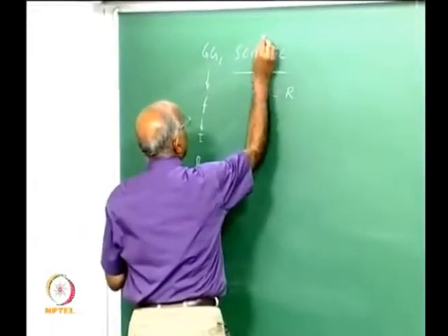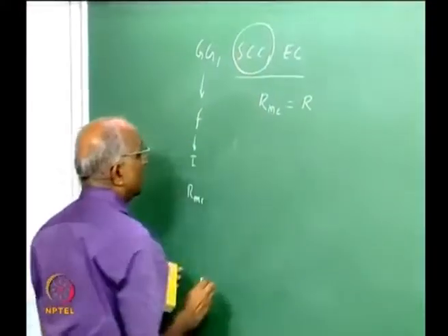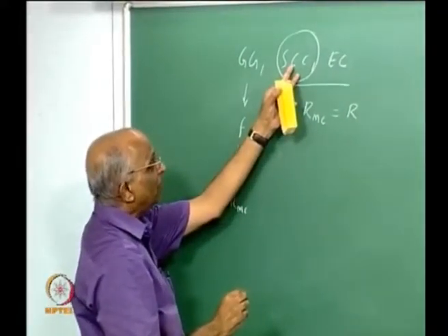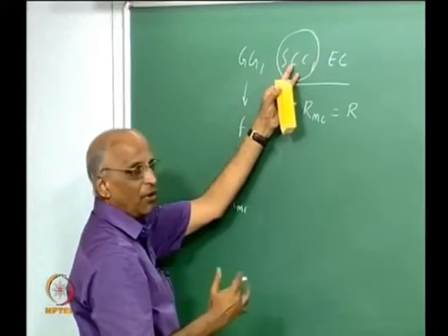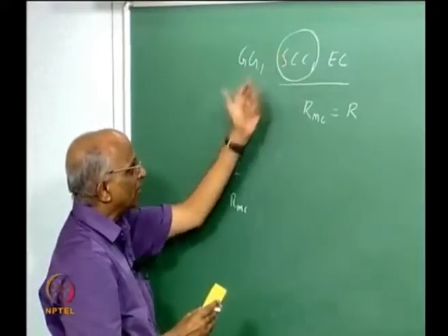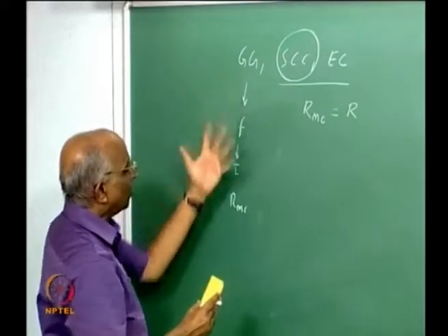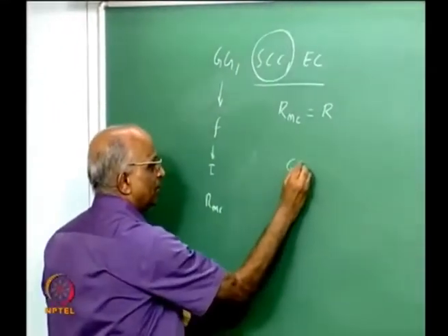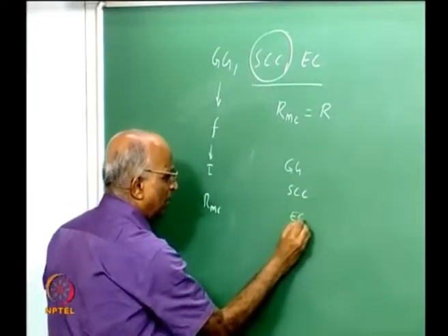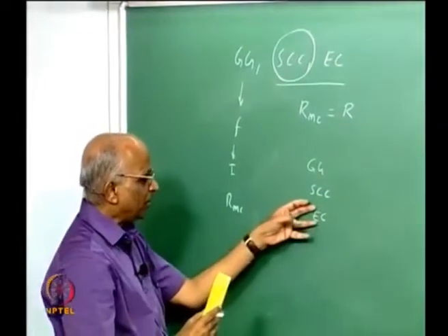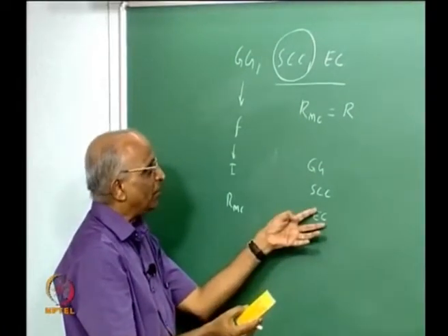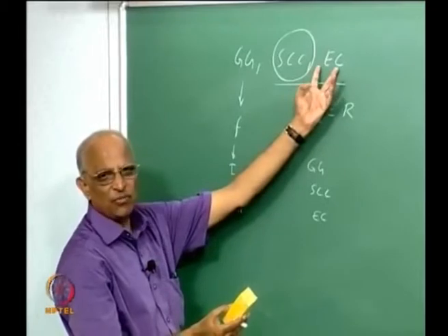For high pressure, staged combustion cycle is particularly useful because I gain the advantages of high pressure, but we will have to take a look at the design of pumps, which we will take a look at after 2 or 3 classes. I think this is all about the gas generator cycles and the staged combustion cycles, and in expander cycle we cannot operate at high pressure because we use only a vapor which is generated by heating of the chamber, but this also has some powerful implications.